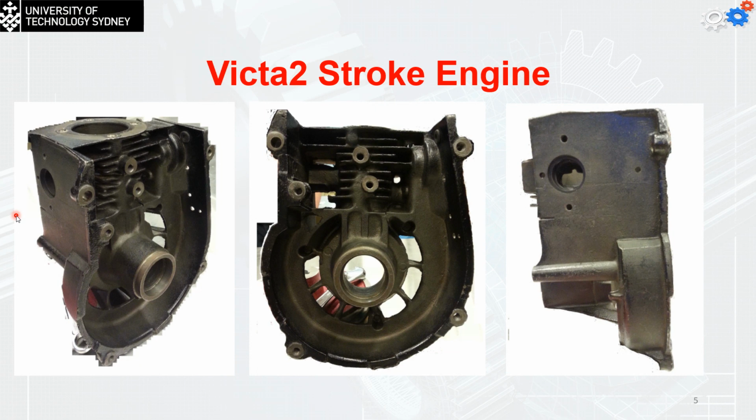Solid shape with two main details. The main details we have: you can see that we have the cylinder bore here. We have the gas outlet on one side. We have the air mixture with the fuel from the other side. We have the seat for the crankshaft at the bottom.